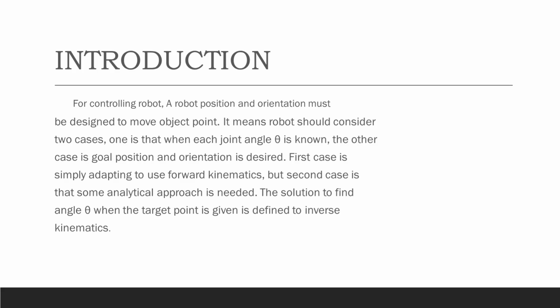Inverse kinematic cases can also be distinguished between the analytical method and the numerical method. The advantages of using the analytical method are that the solution is always correct and the calculation time is fast. In the numerical method case, the advantages are that it is flexible to adapt to DH parameter changing systems and high degrees of freedom.